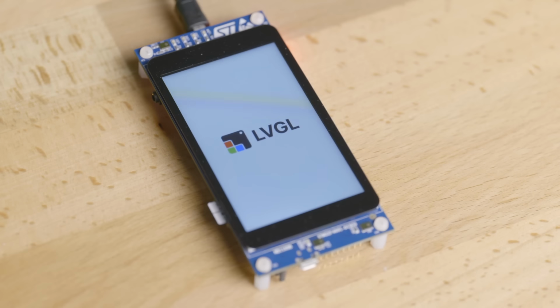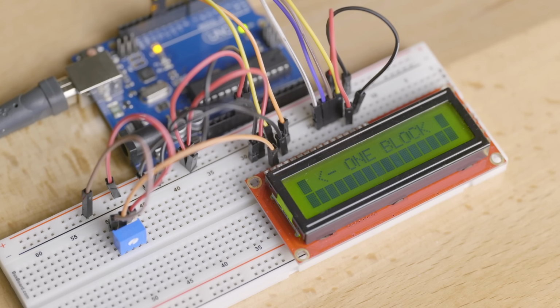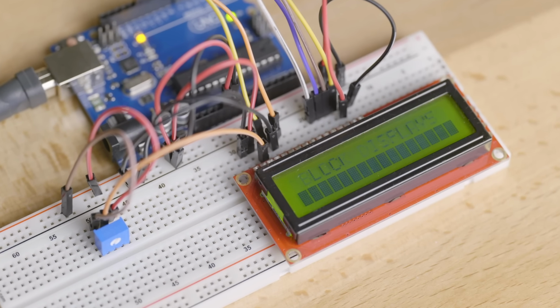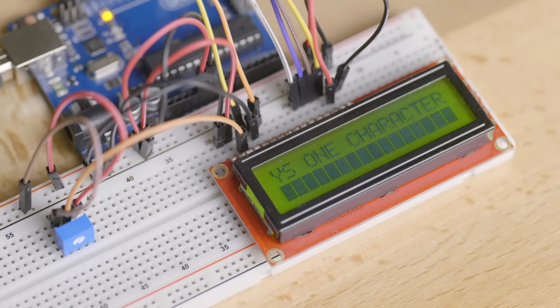What I've just described is how each pixel behaves, but another consideration is how the pixels are controlled, which is independent of the type of display. There are 2 main options: character displays and graphical displays. A large portion of what most people do with displays is show text, so character displays take advantage of this to make programming much easier. Rather than arranging the pixels in an equally spaced grid, character displays arrange them in blocks of pixels, often 5 by 8. Each block is intended to display a single character. You don't control what the actual pixels are doing in each block, instead you tell each block what character to be.